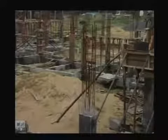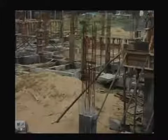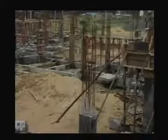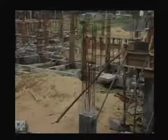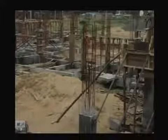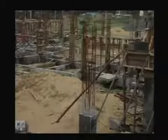This is another aspect from the site, I have just taken this particular one, and here also you can see the construction is going on in our campus itself. So in this particular construction, you can see the tie beams, there are so many tie beams here. Why do we need that one at the bottom? Because from there that brick wall will be started, so that particular one we have to use.